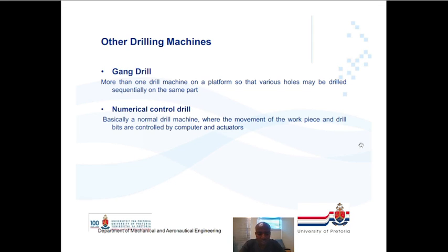That will be good for you, instead of using one drill and changing the drill bits every time you need to change the hole size. Therefore, you might just want to use a gang drill for that. Otherwise, the catch is that if you have several holes that you need to punch on your component, you need to clamp it down and unclamp it. But there are devices that you can use that will help you to hold your component very quickly and very easily.